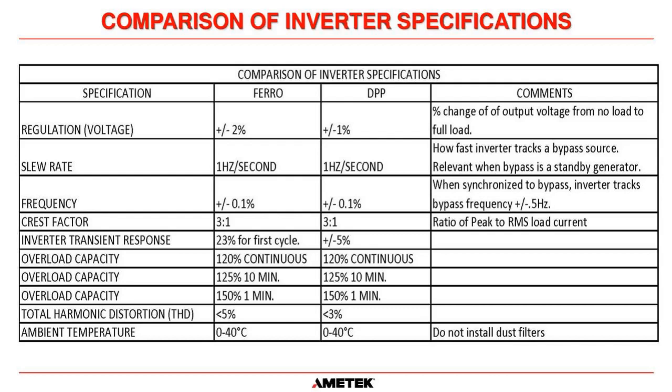Most any room you see out there, it's not really all that dirty. And if we're able to do our annual maintenance on these, or whenever you have planned outages, we go in there, do all the inspections, and that's a good time to clean the machine out, clean the dust out of transformers and fans and things like that. But the machine is put out there to sit there and run and not cause trouble. So we discourage dust filters there. If the room gets a little bit warm, so be it. The thing should keep running. It's there to protect your load.